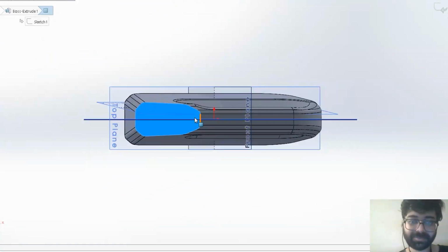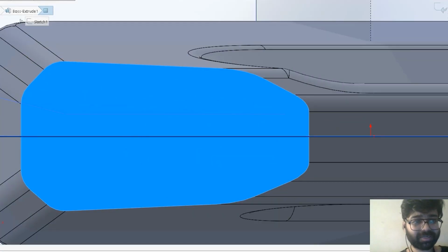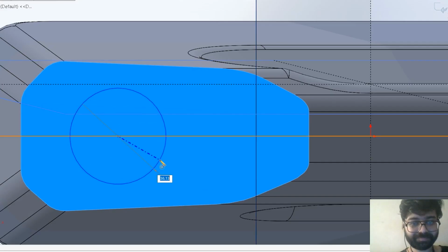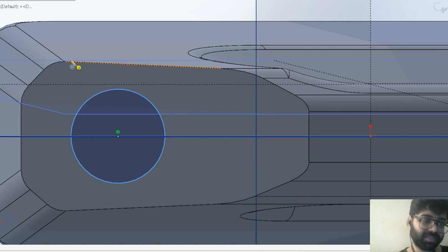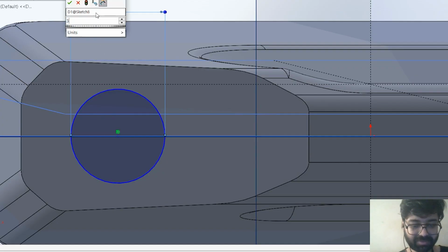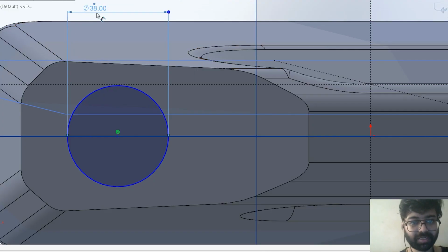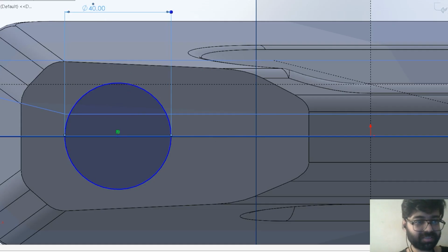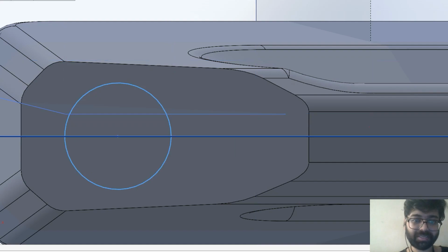So this face I'll take, and mostly I'll go for a rounded one. So you can see I'll go for a round shape here, and that is simple. If you want, I can create a different shape also, but I'll go for a rounded one here. Dimension, let us give it around maybe 30, 35. So it is around 3 cm. Yeah, that's okay. 35 or maybe 38 for a larger one, if you need a larger mouth or something. But yes, try to keep it away from the edge so that later on fillet and all also you can give without any errors.